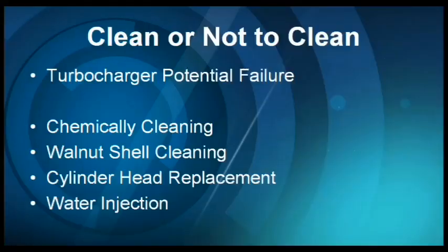But I want to remind you what we looked at earlier, that the alloy of the turbine is over Rockwell 60 tested. It's a super alloy that's being used. So we're at a point here, do we want to make a choice? Do we want to risk possibly damaging the turbocharger, or what are some options that may be out there? So let's look at what our options are that are going on in the industry. One is chemically cleaning. We have to concern ourselves that we're not going to do any damage to the turbocharger.